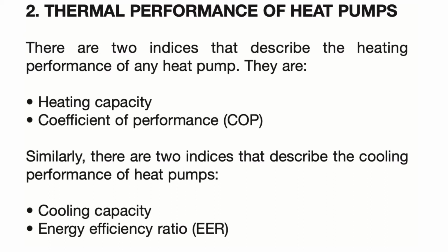And the energy efficiency ratio. The reason for the energy efficiency ratio is so that these units in their cooling mode can be compared to conventional air type of cooling systems. And you will note that their energy efficiency ratio is extremely high because the sink always is cool. The problem with conventional air-cooled refrigeration systems for cooling a house is that you are trying to dump heat with hot air into hot air, and the performance when it's extremely hot outside is extremely low.